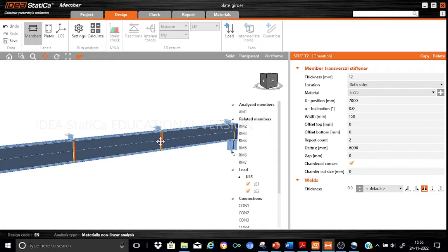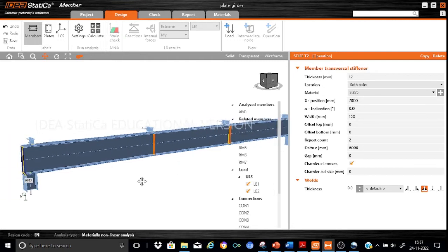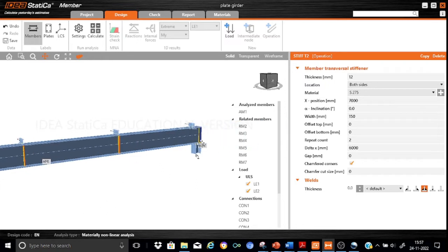However, if the designer feels, yes, for adding to the factor of safety, he can provide some at a nominal distance. For example, he can provide say 3 stiffeners here at 2000 mm. Anyway, I have not modeled any stiffeners in the center portion. Now I'm going to model some internal stiffeners in the left portion, that means between the load stiffener and the bearing stiffener in this zone, as well as on the right side zone. So let us go in the same way.